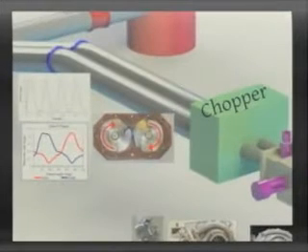I have a device, which looks rather good, that one there. I have a set of plates with openings. When the openings are in line with the pipe, it has flow; when not in line, there is no flow. So I'm able to do on, off, continuously at a given frequency: 20 hertz, 100 hertz, whatever is the time domain that I choose to evaluate. I produce pulses, changes in mass flow and pressure. So I'm capable of shaping this pulse, taking an amplitude and changing the frequency.